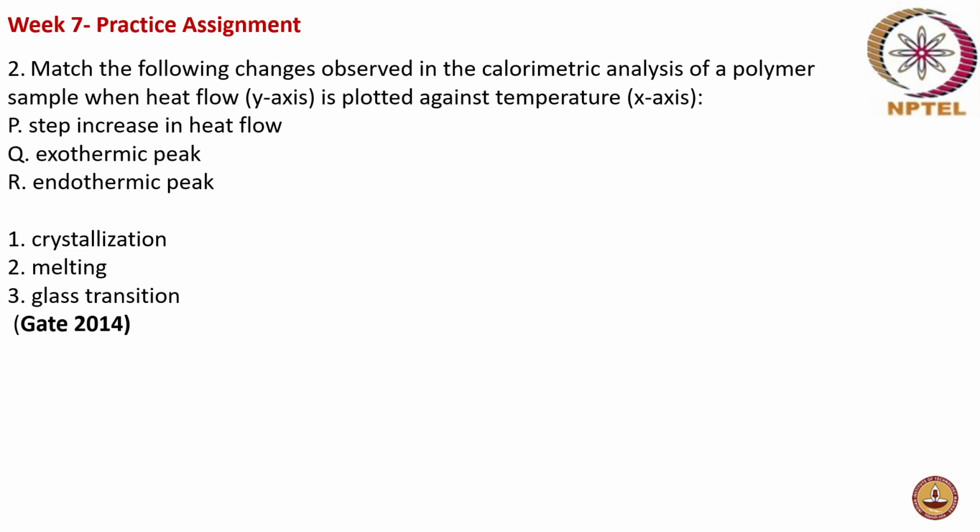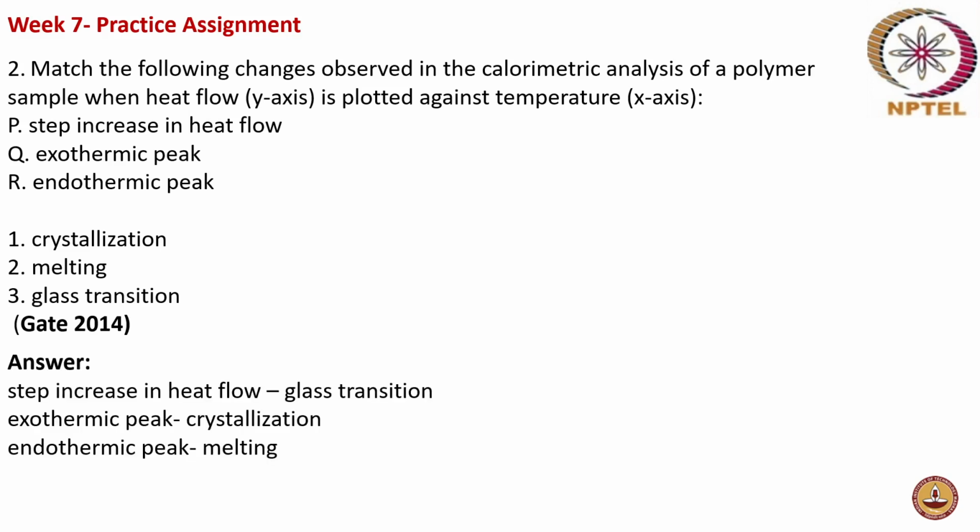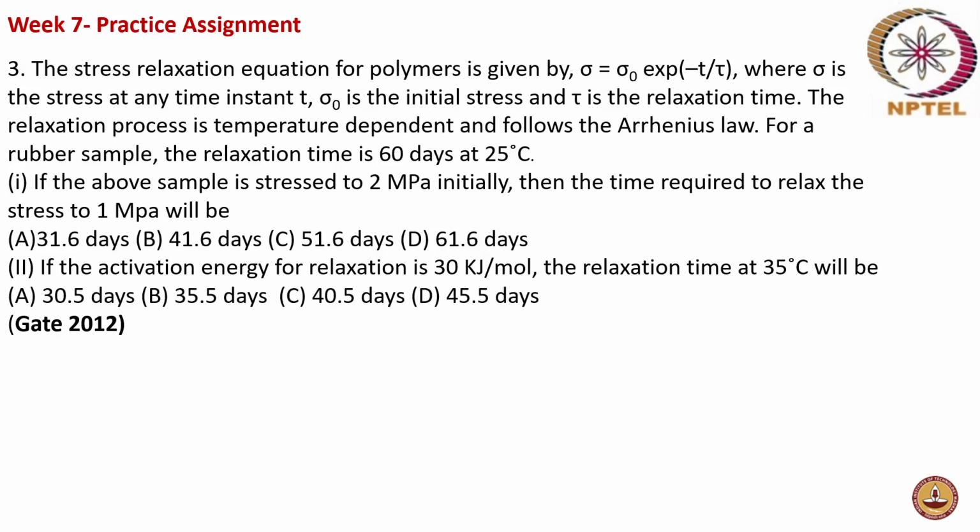Crystallization is exothermic, and melting is endothermic. Yes, you are perfect. So your step increase in heat flow is for glass transition. Your exothermic peak corresponds to crystallization and your endothermic peak corresponds to melting. Fine. Let's go to question number 3.